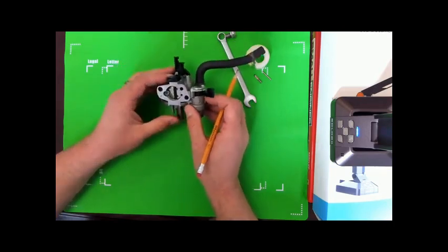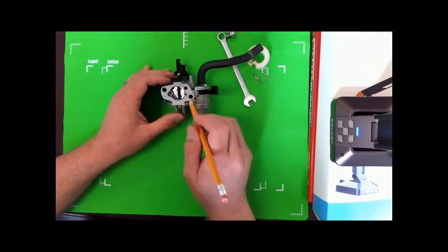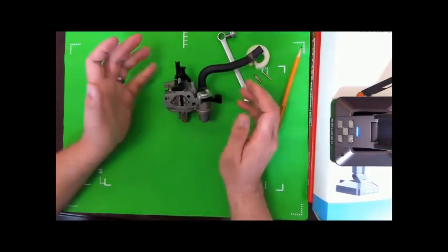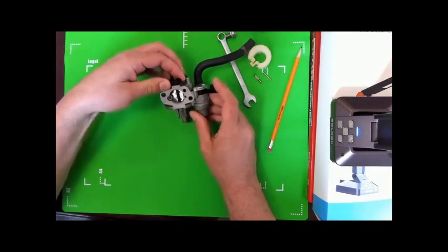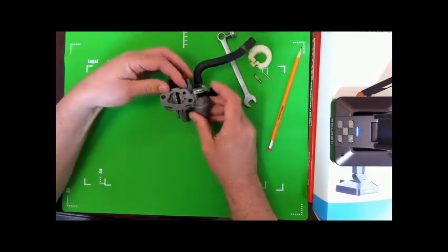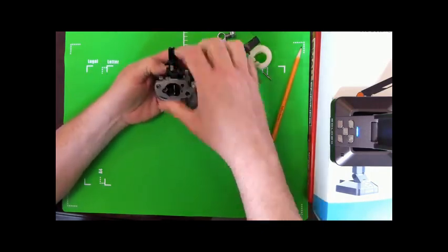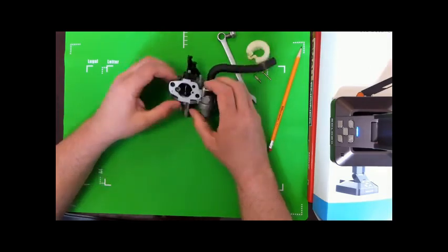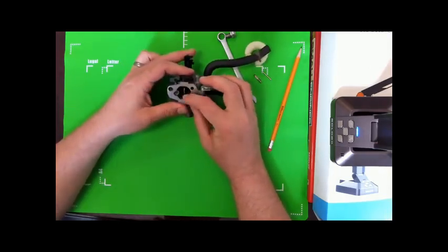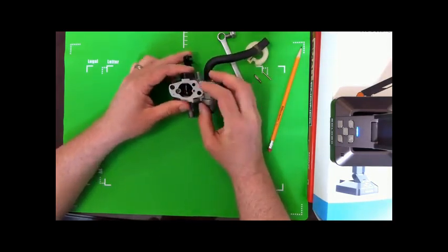I've said the word jet several times, and we can also think of these as ports, and this is going to be where airflow is regulated. In a few minutes, you'll see a video that's going to do a pretty good job explaining how these carburetors work, but in general, I will go over it very briefly. So with our choke off, this is what it would look like. This choke plate is essentially not doing anything right here as far as airflow restriction.